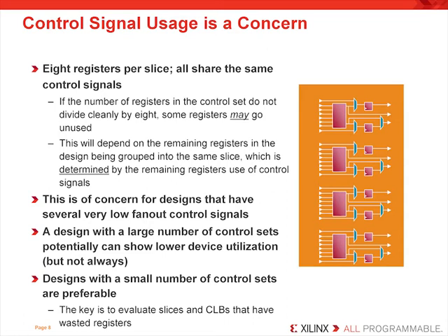So if you cannot anticipate that you may have too many control signals, keep a lookout after implementation to see if there are many slices that have unused registers. If so, you may have a problem of this nature. Now note that VCC and ground are connected to each unused port, that is the set, the reset, and the clock enable, etc. So if you are not using the set, reset, or clock enable port, that port will be tied either high to VCC or ground. So VCC and ground are also considered control signals and can be factors in preventing flip-flops from being used.